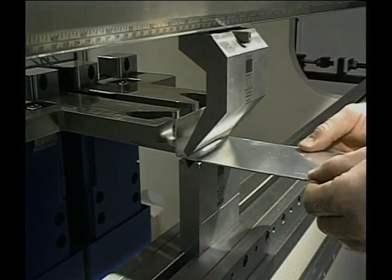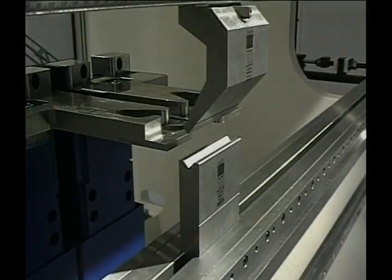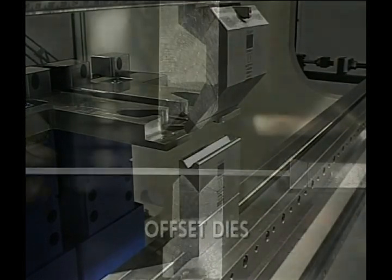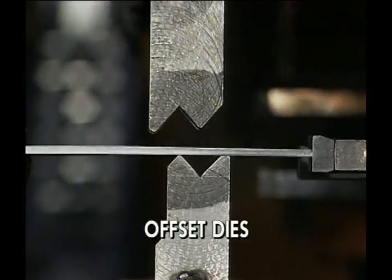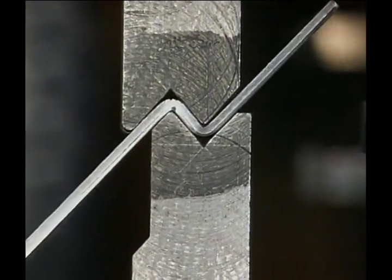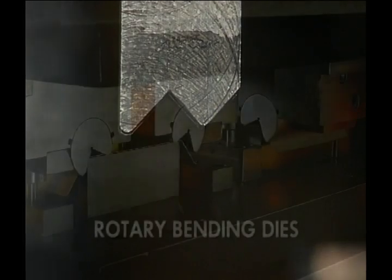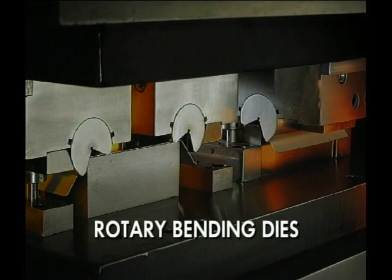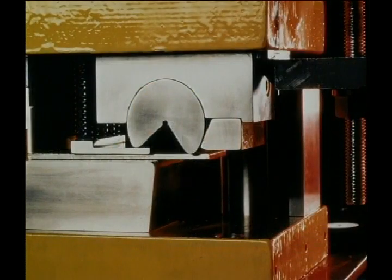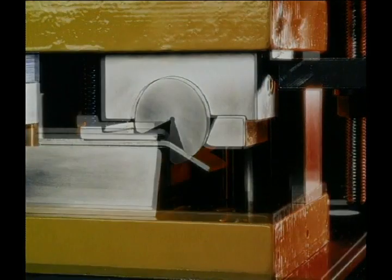Since the neck of the die is usually out beyond center line, care must be taken to prevent overloading the die. Offset dies are typically used for long runs and require from 4 to 20 times more force for a single bend, depending on the nature of the offset. Rotary bending dies use a cylindrical rocker with an angular notch cut out along its length. As the punch descends, the rocker clamps the workpiece and bends it around a die anvil.